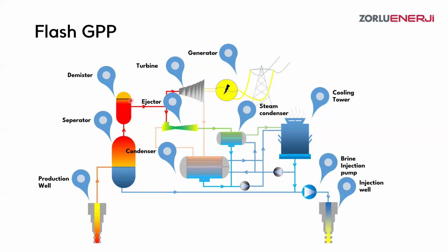to another piece of equipment which is called a demister. Basically, this equipment is trying to remove as much of the water or liquid from the gas section as possible, because this gas has a very high value of energy, and due to that energy it holds some of the liquid from the separation process, and here we are eliminating those droplets of liquid as well, and afterwards it follows this line and goes to the turbine.